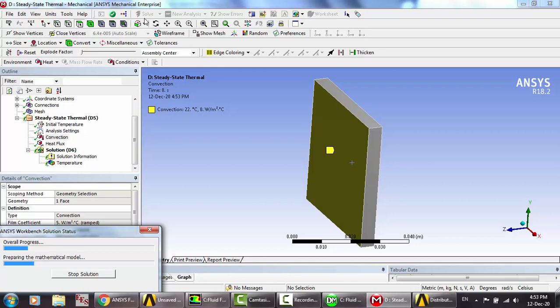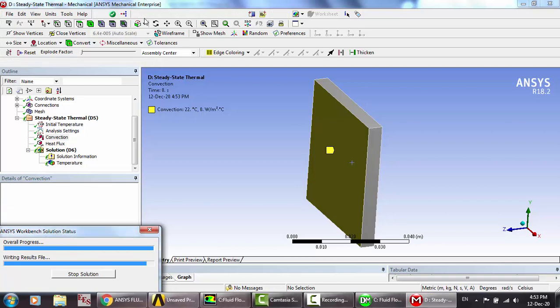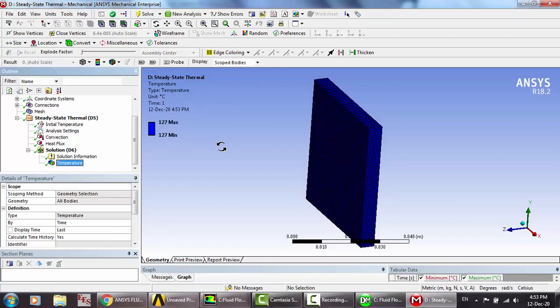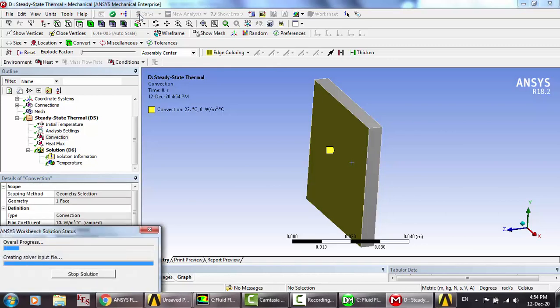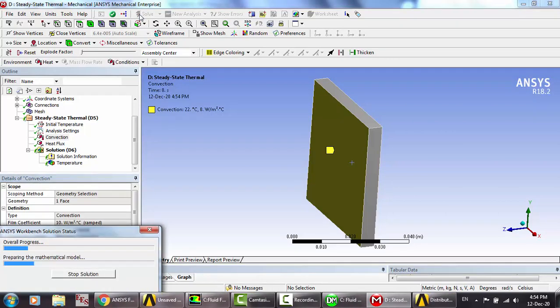This means that the convection is not affecting the surface significantly. As you can see, it increased when we decreased the convection. But this is only if the heat flux is fixed and the free stream is fixed. Now, if this is 10 and we decrease this, the temperature, of course, will decrease. You know, the free stream is very, very critical. It's a very important factor.